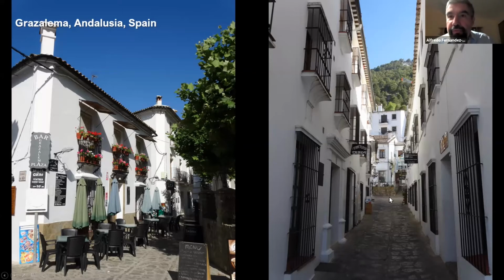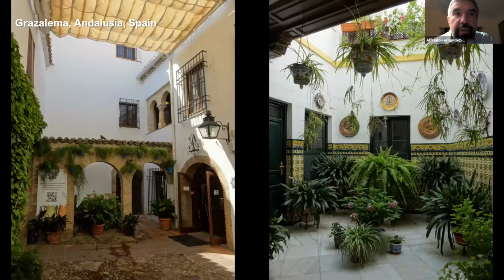On the photograph on the right, you can see a narrow street, typical of this kind of climate. It remains cool during the daytime because it's in deep shade, surrounded by heavy mass materials. And we gain illumination, ventilation, and privacy, all through the use of courtyards as a strategy in this type of climate. So here you see the vegetation, oftentimes evaporative cooling also deployed, having shade through the movable toldos and awnings. And of course, we can get ventilation and cooling that way.